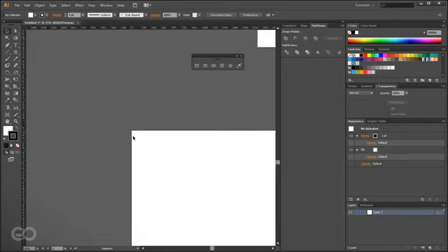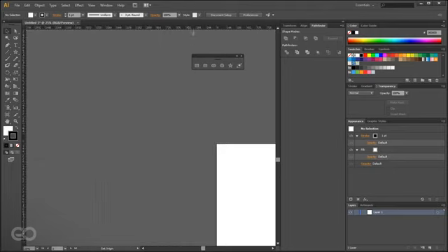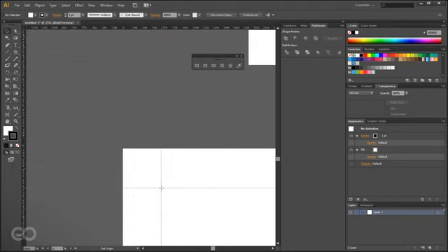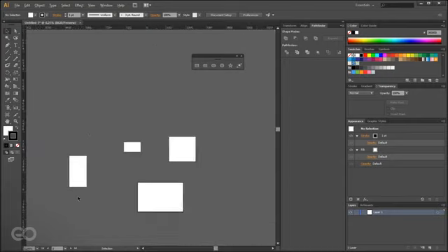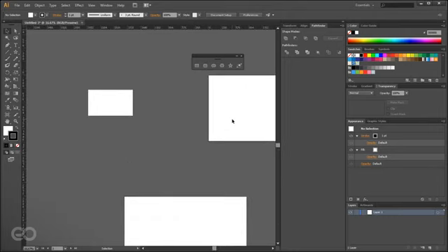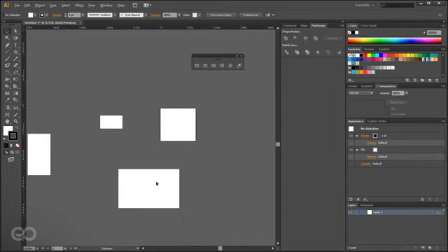So if you really want to change the position of these, you can just go to the corner of the rulers, click and drag, and pay attention to the top and the side of the rulers. When I let go, you can see the 0 points have shifted. Wherever I keep this is where the 0 points are, but it does not change that for any other canvases. So if I come to a different canvas, the 0 position is still exactly here at the corner. This is because each canvas has its own local set of rulers.